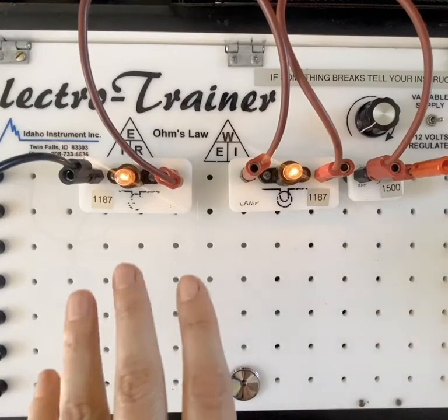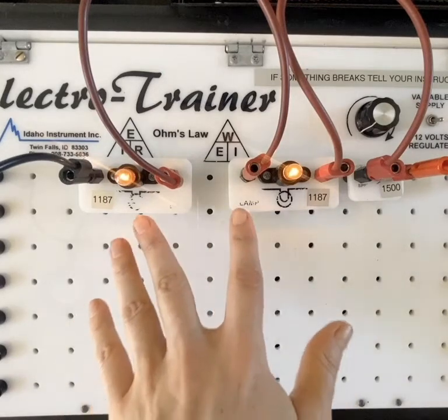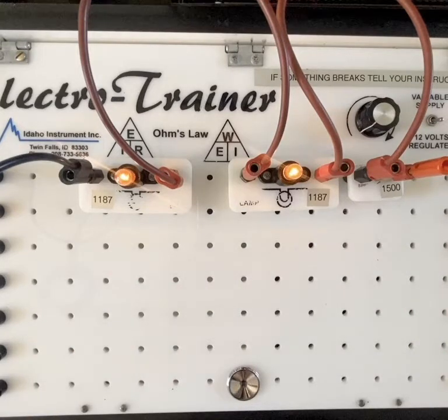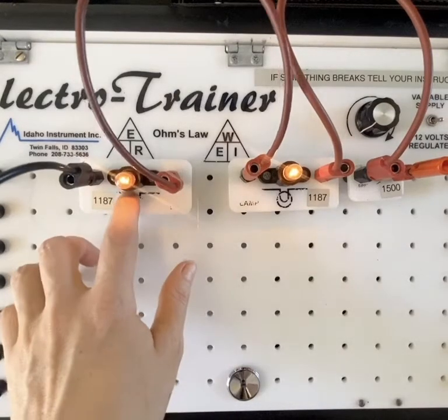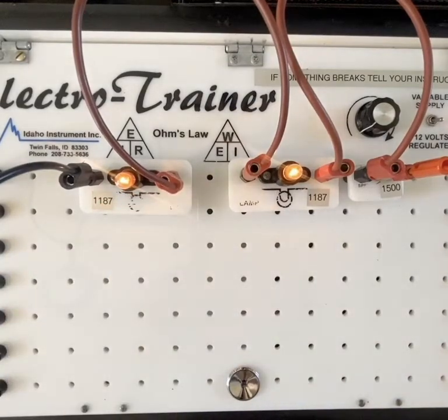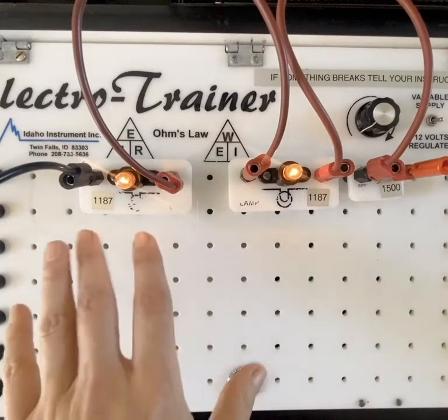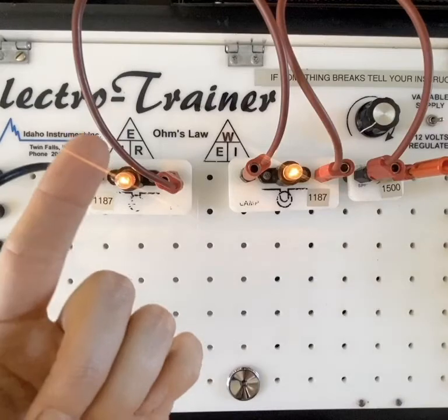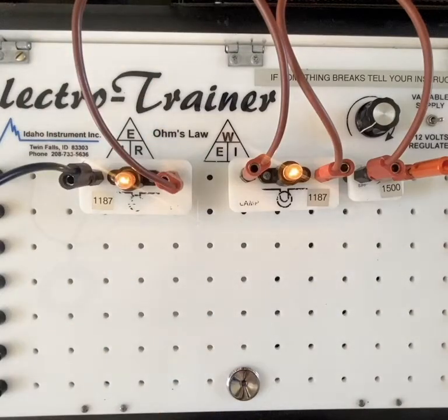We know that we are looking at these two bulbs dimmer than the brighter one bulb for a few reasons. And I know I'm kind of repeating myself here, but it's important to remember, since we added another load in series, we increase resistance, and we remember from parallel circuits that wasn't the case. So we added a load in series, which increased our TCR, which we know through Ohm's law decreases our TCA. So off the bat, we're dimmer partially because we've got a couple things going on.